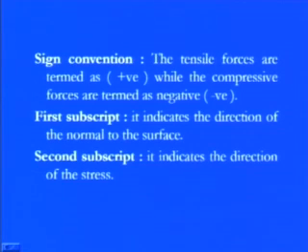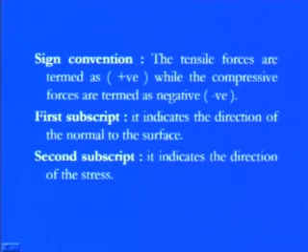So if we are talking about the normal stress component, then we always need to choose the tensile stress as positive and the compressive stresses as negative. But if you go back to this concept, we found that whether you are working in the x domain, y domain or z domain, the stress components, if it is in the x domain, were sigma xx, tau xy, tau xz. That means in these three stress components there are two subscripts, for example sigma xx, tau xy or tau xz.